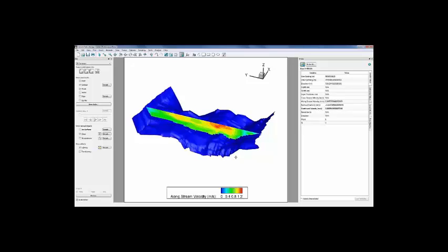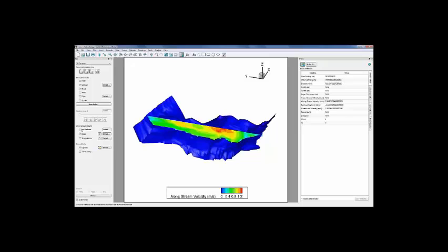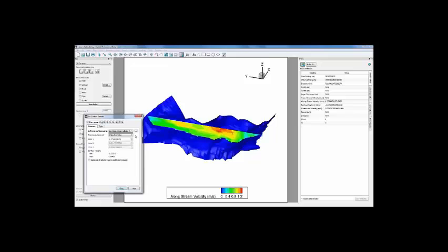Another effective way to kind of look at a flow field when you have volume data is to use isosurfaces, which is basically a constant value. Here we're kind of turning on the isosurface of along-stream velocity, so we can kind of step through the different values, and it'll give you some interesting insight into some thresholds depending on what you're analyzing. So that is an effective way. Maybe I'll pause there, and Art, do you want to comment on the slices and the isosurfaces before we jump into the stream traces?